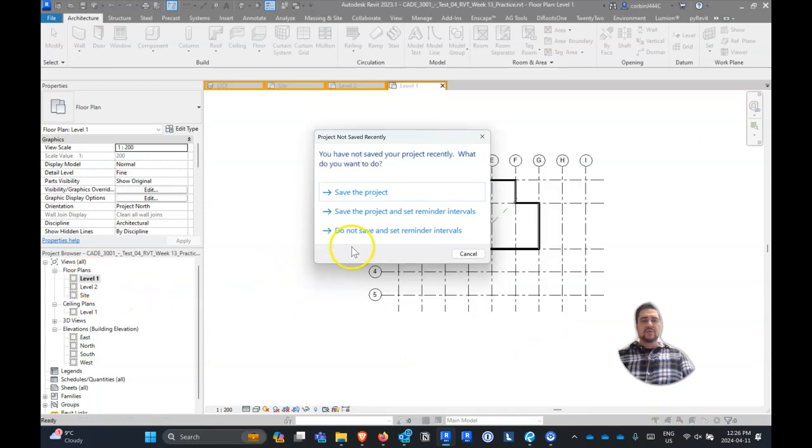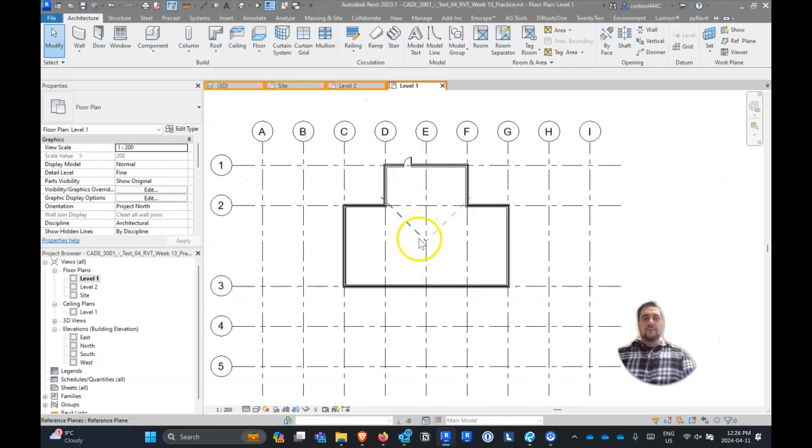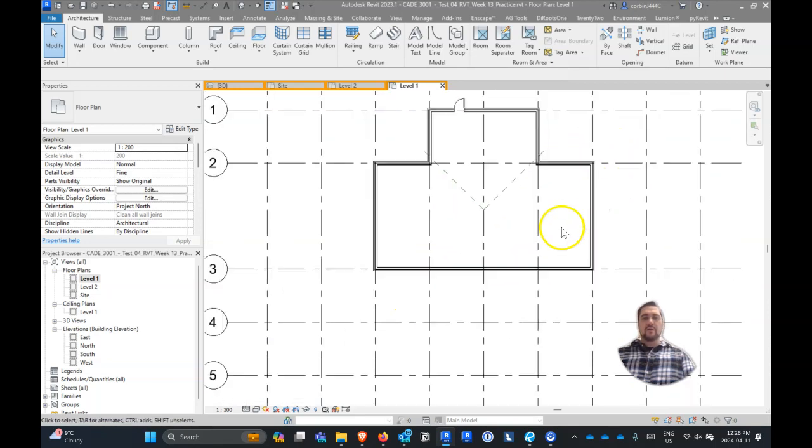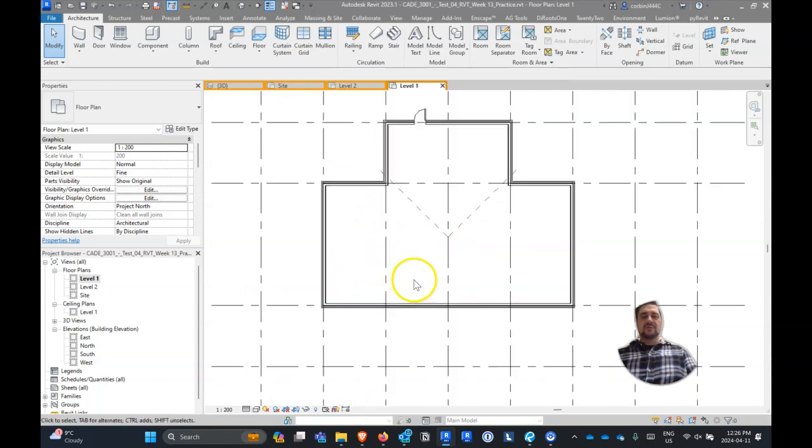So we're going to go back to our first floor plan, and we have our building here. Our grids are oriented to the outside of the stud wall. That's kind of another practice. When you're dealing with maybe more wood frame construction, obviously in big commercial construction like you're using in your studio projects, you want to center structure on the center of the grid. But sometimes in residential, when you're doing wood frame construction, we either do the center of stud or sometimes we do it to the exterior stud. So not a huge deal, just there might be different standards for that.